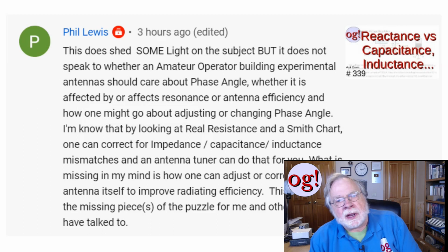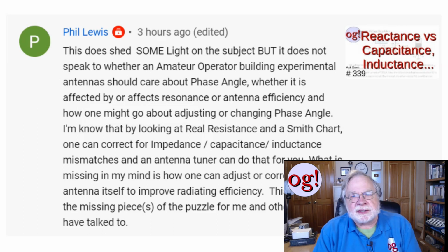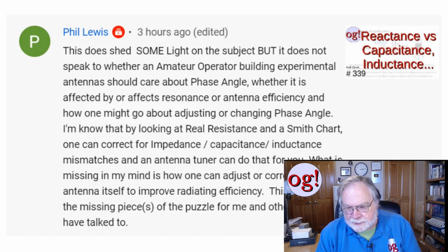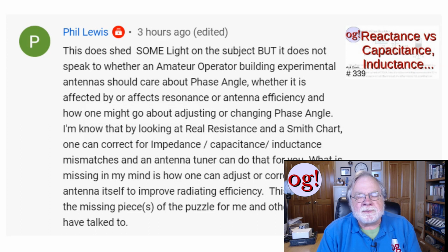Now, every antenna has two kinds of resistance. Ohmic resistance, which is the losses, the ohmic losses that come from heating either the transmission line or the antenna itself. Those are losses you don't want. On the other hand, there's another kind of resistance, which is the equivalent resistance of the power that is radiated. So you want your radiation resistance to be much higher than your ohmic losses.